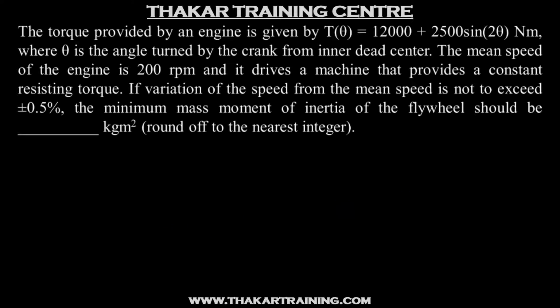Now, in the earlier video on flywheel, I had mentioned that the crank rotation angle for one cycle of the engine will be given in the question. If you have watched that video and understood properly, the crank rotation angle for one cycle is required mainly for two purposes. One, to calculate mean torque, and other, to find fluctuation of energy of the flywheel in one cycle. But this question does not mention anything about the crank rotation angle for one cycle. Then how do we solve this question?